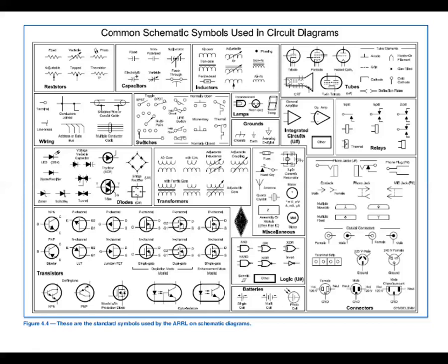All that is an electromagnet that energizes to open and close a set of contacts. So it's just like a hand switch that you could move between the 2 points. Instead of doing that with your finger, you can energize the coil of the relay, and it'll pull the wiper arm down to this contact and connect that circuit.